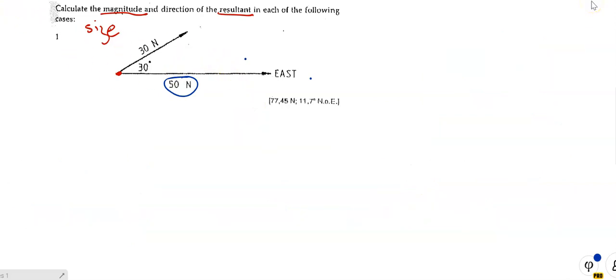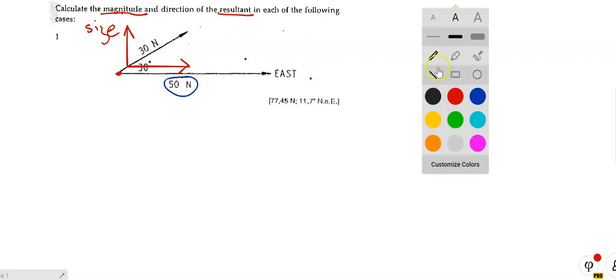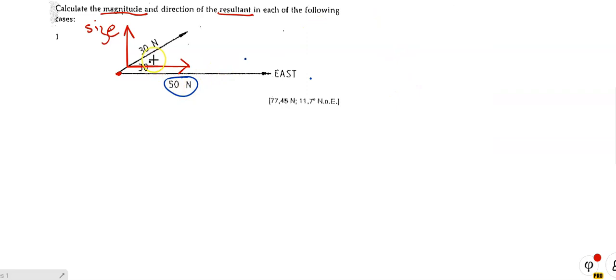Right, people, now we know about sign convention. We know which way the forces go, which way the moments are going, but we get to moments later. And we also understand how to call out the directions, and we know how to resolve components. Now, I'm going to resolve my forces on my sketch over here. There's my vertical component of that force, and that's my horizontal component of that force over there, like so. Okay, and I'm going to name it. If that's 30 degrees there, that's 30 degrees, agree with me there.